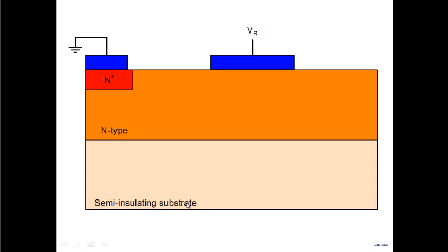Okay, look at this particular picture here. What do we see? Two kinds of contacts. What will this be? It's like a good contact, ohmic contact. We will call it an ohmic contact in the sense that very little voltage drops here. And this will be a Schottky barrier diode here. Will there be a depletion width? Yes, right? If I apply a higher voltage, what will happen to the depletion width? It will increase. Can you think of an application of this phenomenon?